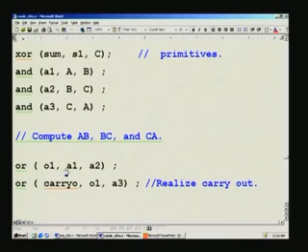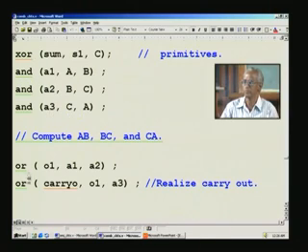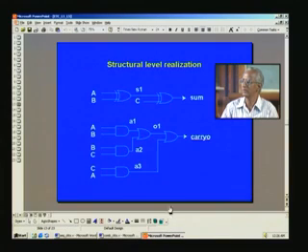These are all the intermediate signals S1, A1 through A3, O1, and they have exactly the same meaning as the exclusive OR. Always write the output followed by the inputs, for a 2 input AND operation and a 2 input OR operation. These S1, A1 through A3, O1 are precisely the intermediate outputs that we have used.